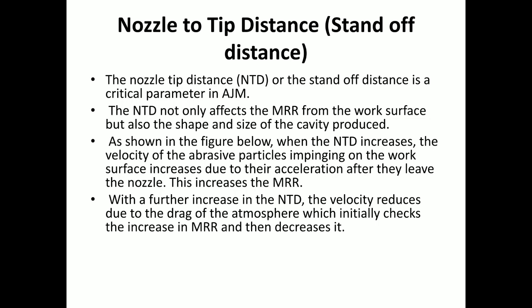Means it is not only affecting the MRR from the work surface but also the shape and size of the cavity. Very important, shape and size. If we change the nozzle tip distance, whatever shape we are requiring may or may not be produced, depending upon the NTD.